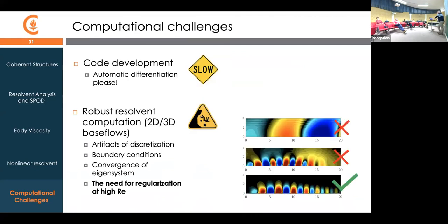Another thing I want to highlight here is that whenever you're doing numerical linear algebra, you have to worry about conditioning. And with resolvent calculations, one of the things that can be very problematic are the boundary conditions that you have on your compressible, in our case, Navier-Stokes equations. You have things like non-reflecting boundary conditions, inflow, outflow conditions, and so on. And we know from boundary condition work going back decades that there are lots of different spurious modes that can be excited by imprecise or not good boundary condition treatments. And we also know that those things can interact in a very substantial way with the numerical discretization itself.